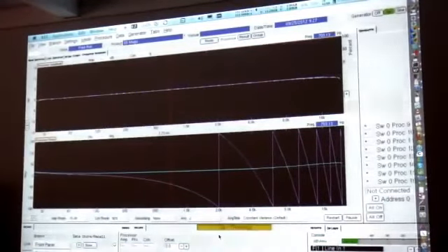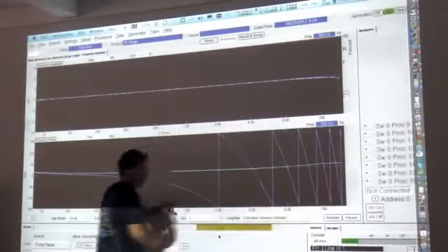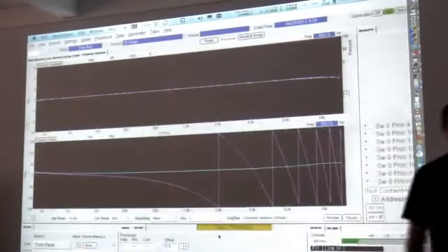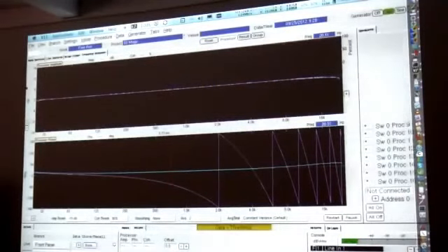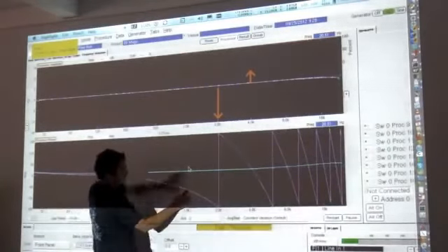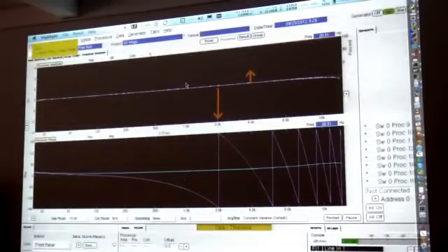Remember vocabulary. Number 2. Phase. What happens if the phase difference is 180 degrees? Cancellation. So this means that in this frequency it will be cancelled. But what happens when the signal is 360 degrees? Summation. How many decibels? So here, 6. But what happens when the phase difference is 90 degrees? Plus 3. So here the signal will be exactly here.